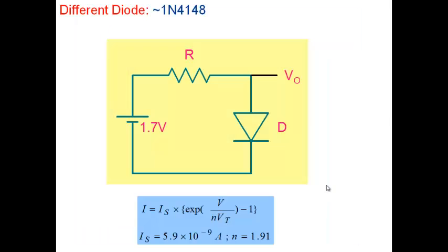And some differences also come about because the ideality factor N is 1 here, and in the other case, N was close to 2. Now, how come the two diodes have different values of saturation current? Well, these diodes are PN junction diodes. So one of the differences is that I have different doping. The doping in semiconductors can vary from, let's say, 10 to the power 13 or 10 to the power 14 all the way to 10 to the power 19. So I can change doping over a very wide range. So that's one source of variation in IS.